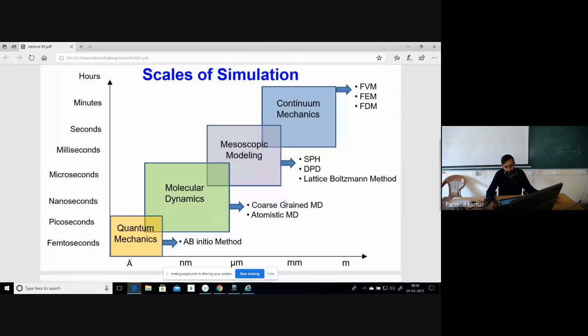If the value of the Knudsen number is greater than this critical limit, then we cannot assume our medium to be continuous, and we have to consider the individual molecular or atomic activities. Okay. If I recapitulate the definition of the Knudsen number, it is nothing but the mean free path divided by the length scale of our physical domain. Mean free path is the average distance between successive collisions.